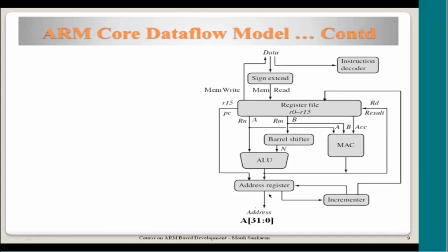It can perform only instruction access provided there is no memory access in the instruction. But suppose we have a sequence of instructions which are all arithmetic instructions like add or subtract, or any operation which is internally done with the register content, and there is no need for accessing any memory. Then the processor can keep on sending the PC value to access the instructions, and it can keep on incrementing it. If there is no jump or branch to some other address, then it can sequentially access the instructions in the memory, and then keep on processing them inside.